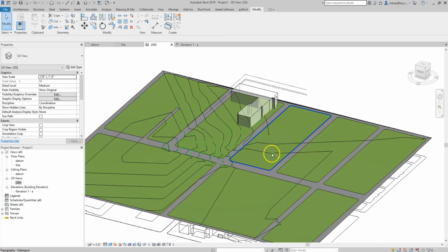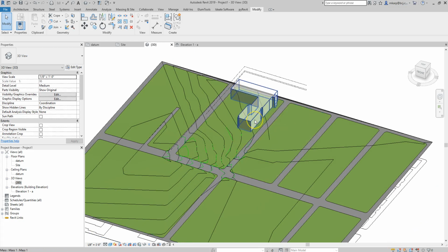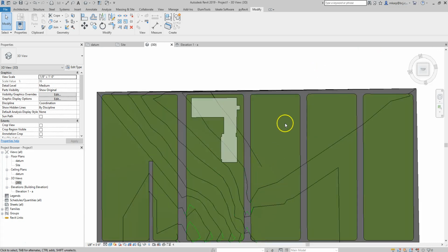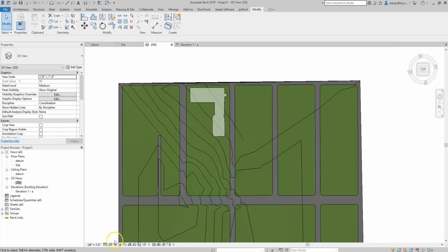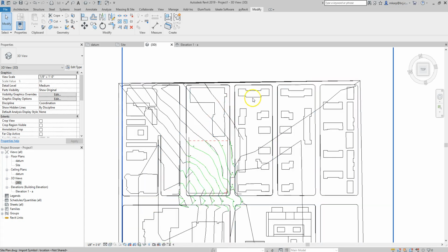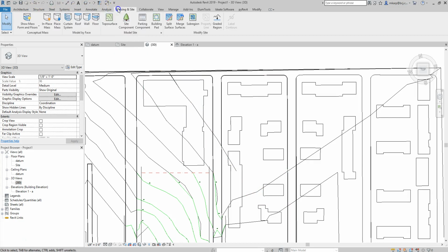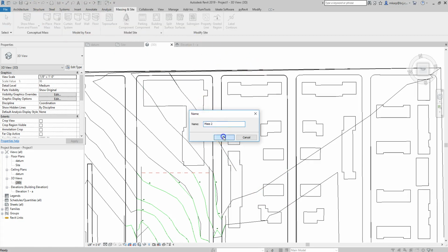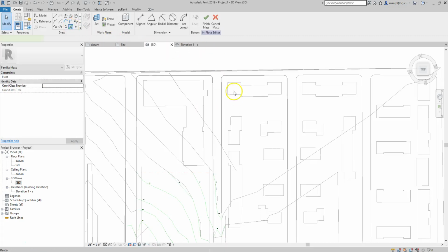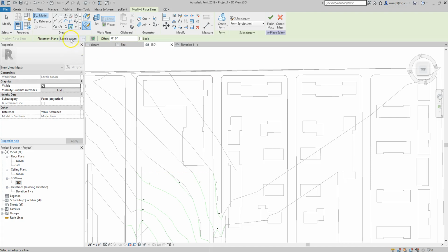So I'm going to make some of these other masses on the site, starting off from the same level, which might not be accurate, but just as a starting point, since I don't have a lot of data on these other structures. So I'm going to go back to a top view, and as a separate mass, make some of these other houses. So I'm going to switch back to Wireframe. And, all right, I might make some of these all together in one mass. Massing, in place mass, mass 2. So we want to make sure we're on the building and drawing on the work plane.